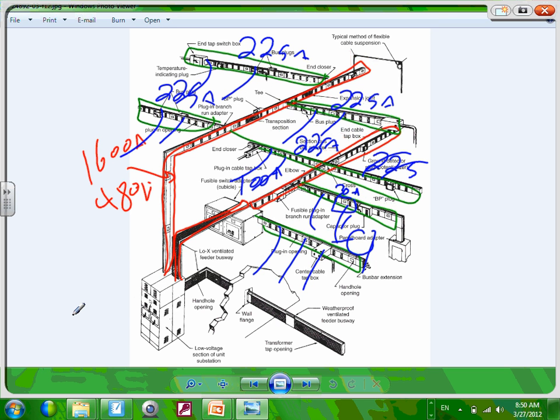The difference between plug-in busways and trolley: plug-in is permanent for the most part. Trolley is movable. If I have a machine that's welding, I will weld here, and also here, and over here. If I tie it to a trolley busway, I can pull that cable while connected to the energizer, and pull it to every location along the track to utilize the machine.